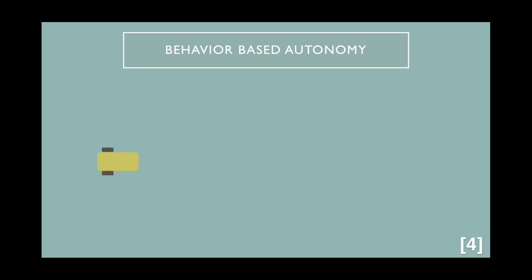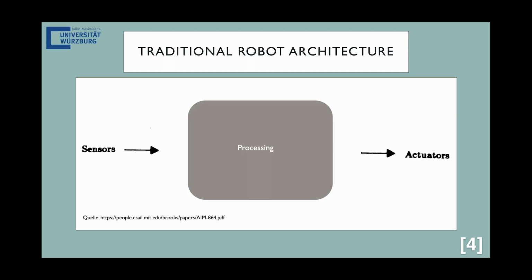An example of this would be a robot with a distance sensor attached. If the distance measured is higher than a certain key value, the robot drives straight. If suddenly this distance measured goes below this key value, for example, if the robot is close to a wall, the robot stops and waits until this distance measured will be larger than the key value again.